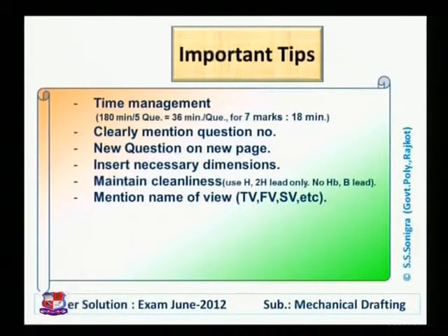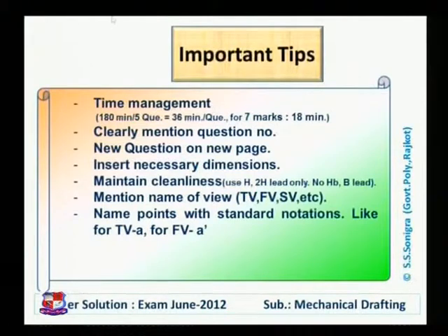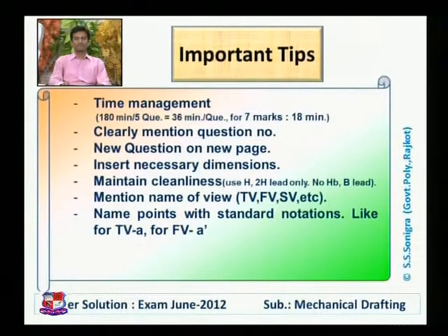Mention the names of views, for example front view, top view, side view, etc. That should be mentioned below the views. Name points with standard notations, like for top view A, B, C, and for front view A dash, B dash, C dash, etc.